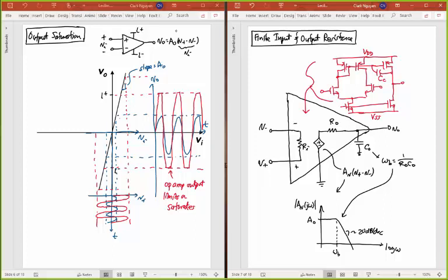Okay? And so in this course, you will learn about these things. These are MOS transistors that I'm drawing right here. And we could also make this in bipolar transistors. You'll learn some of the structure here. Maybe not all of it, depends on how far we get there, but at least some of this structure you will learn. And this is what's actually inside these op-amps. This is the magic that happens there. And because these are real devices, you can never get Ri to be infinity. You can never get R naught to be 0. You can never get gain to be infinity, but you can get close with these types of devices, these transistors. Okay, but for right now, the main point is when you want to simulate an op-amp, this is your equivalent circuit right here.